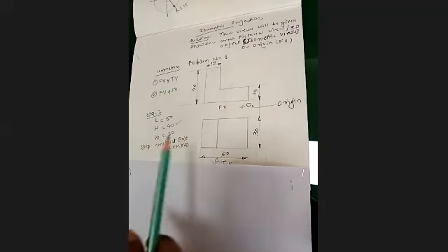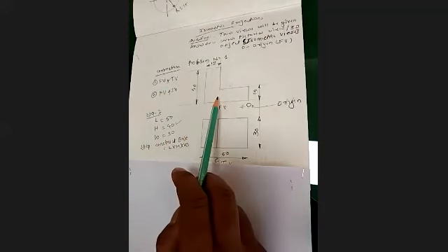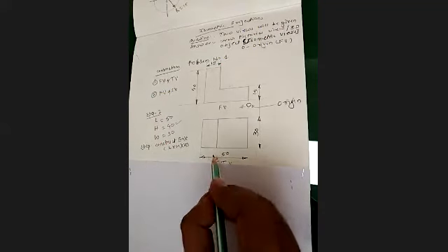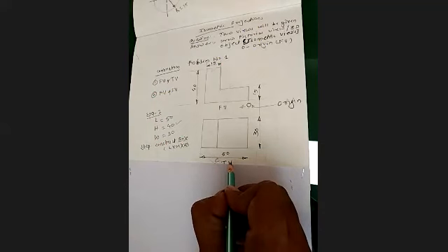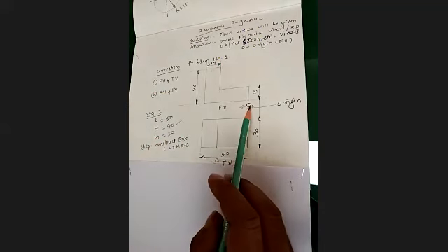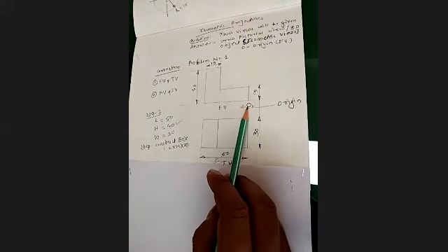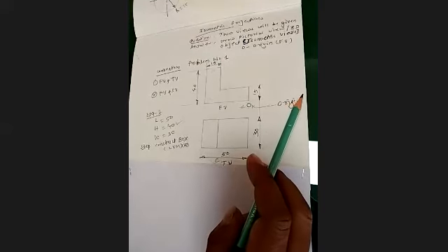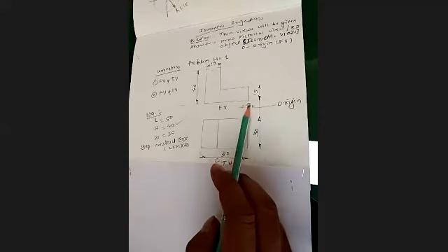By looking at this view, the views will be given to you with the first angle projection method, so that if this is the kind of combination, then the upper view will be the front view, and below that is going to be the top view, right? So two views are here. Now the very important thing, the mention of this O letter. This O indicates the origin. This is very, very important.